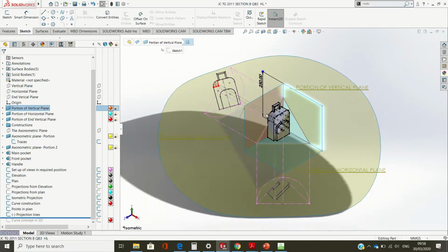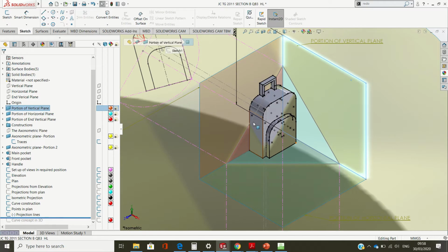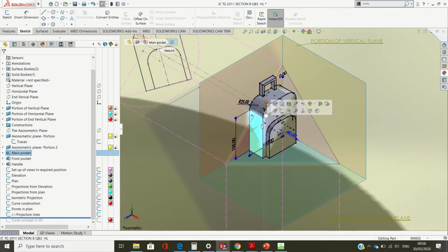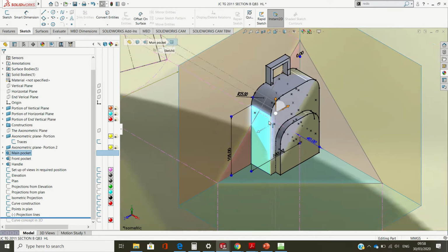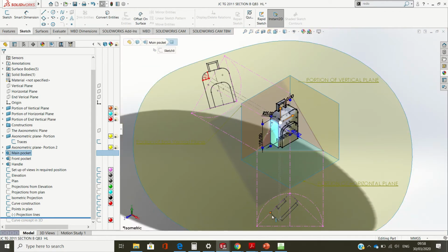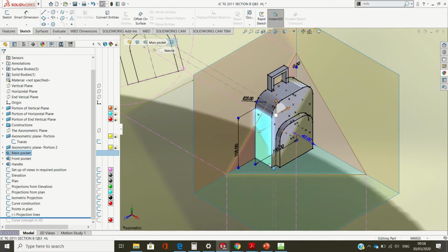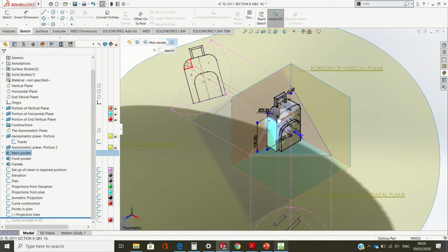So I'm going to make this 3D, into the axonometric projection, by beginning to do this face here. The key ideas will be that these two lines, that I've just highlighted in orange, will appear as points in plan. They'll appear as this point and this point. And this line here will appear as a point in elevation, and these 2 points here will appear coincident in elevation there. So I'll start at this.